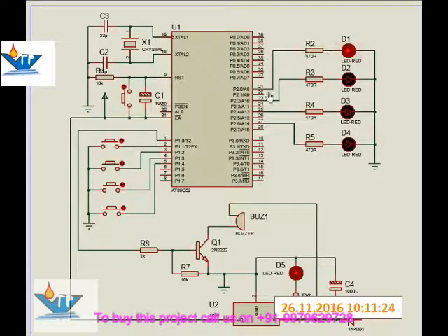The LED is connected with port 2 in forward bias condition. A resistor is connected between port 2 and the LED, while the negative of this LED is directly connected to the negative supply, which is here. The reset switch will not work in Proteus. This is a limitation.